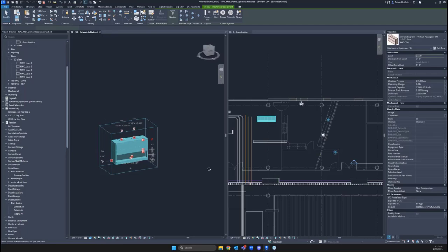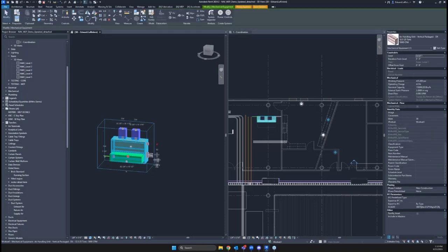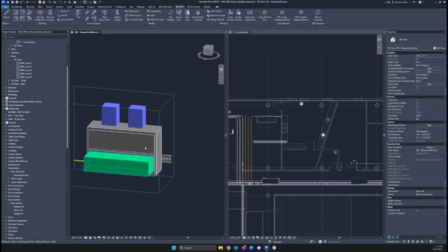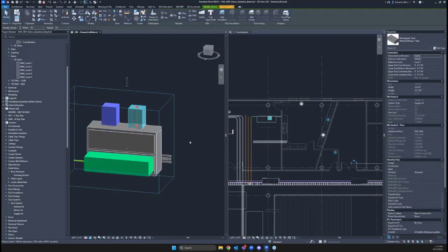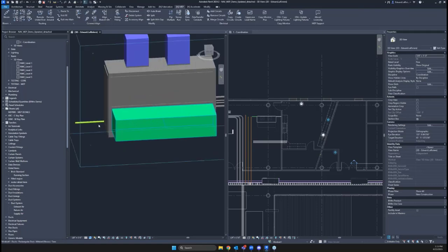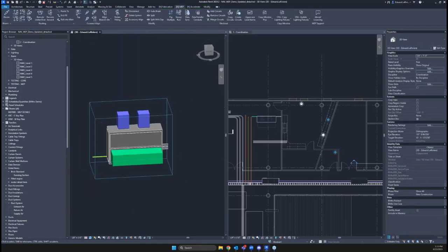And if we take a look at this larger unit right here, we can actually use that Bloom tool against this unit as a way to go ahead and have every single one of those open connectors have something kicking out of it. But because that unit's undefined, there's no real way for it to know that just because that's a supply connector, it needed that exact supply duct. Or if we look down here, that sanitary pipe gave me a sanitary system and a standard pipe type. More often than not, we want something specific here, not just that generic first choice.